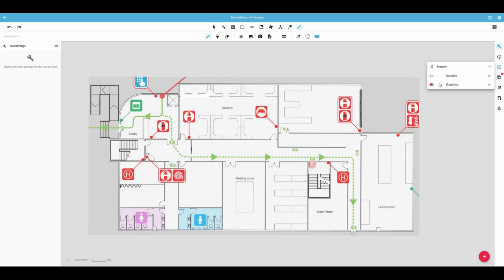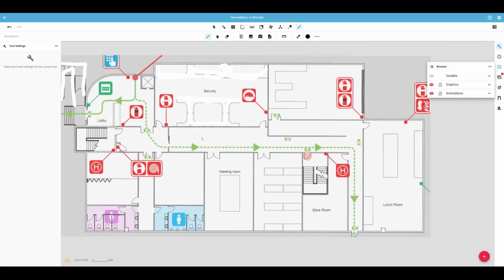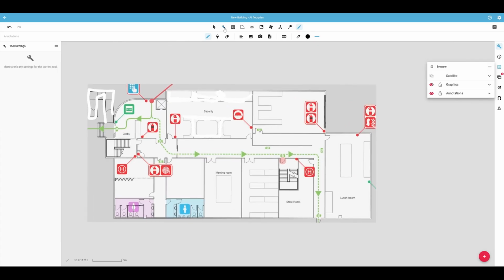This time, what we can do is use the annotation tool to draw over the top of the graphic with a white fill to mask any objects that we don't want the AI to detect, hiding them from sight in the graphic. We can then also use the black annotation tool to draw in any additional wall lines to help emphasize their importance to the AI tool and have them detected as walls, or to simply add in any additional walls you may want to draw by hand.